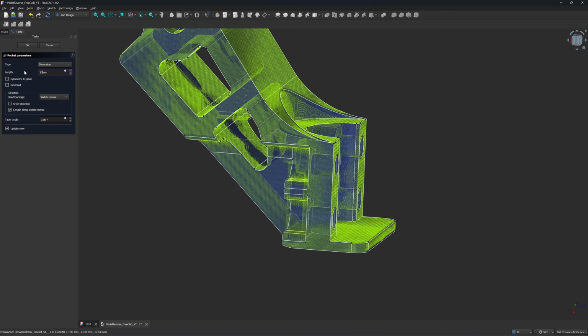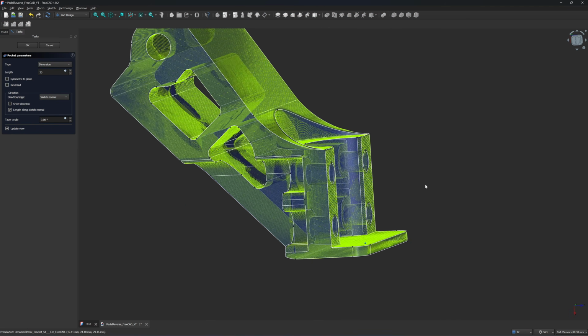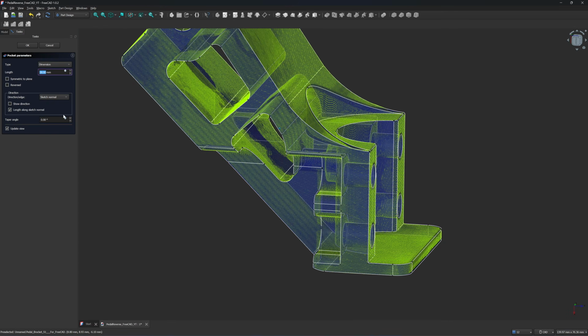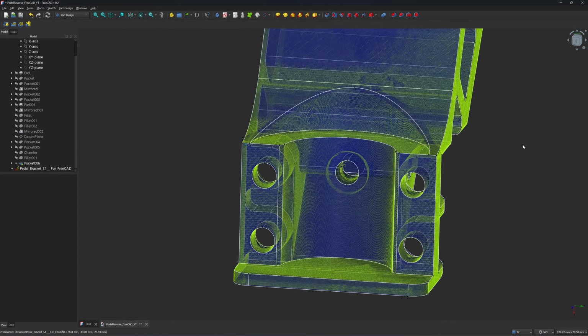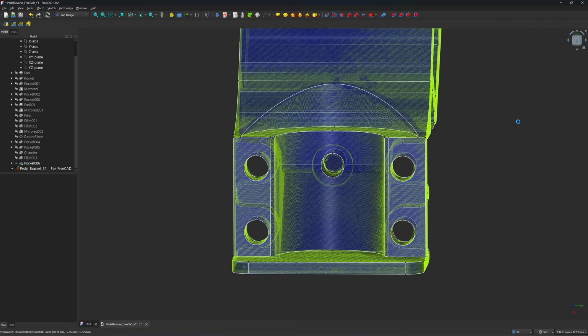I think it's somewhere around 20 millimeter, 30. Okay, now it's 30. At 30, it's going to get into here. Now you can just add 1 millimeter at a time. Okay, now it's past through here. Click on OK. Now you get a hole for the thread, and there's a hole for the counter bore of the screw.